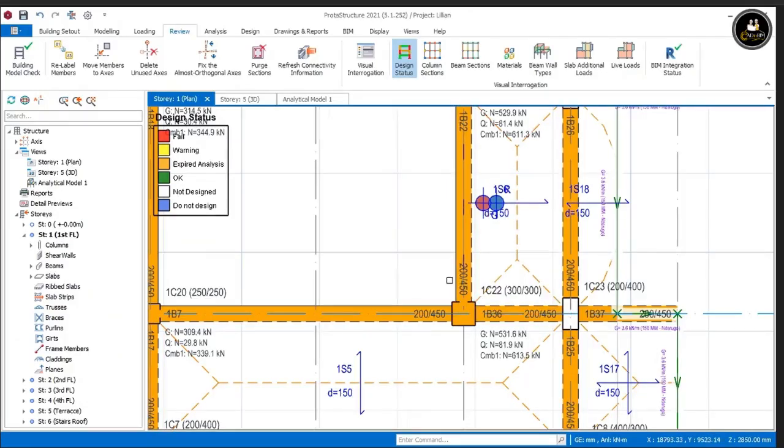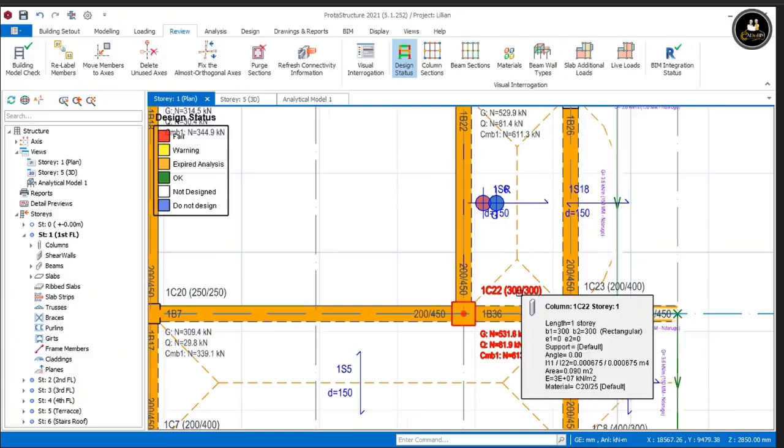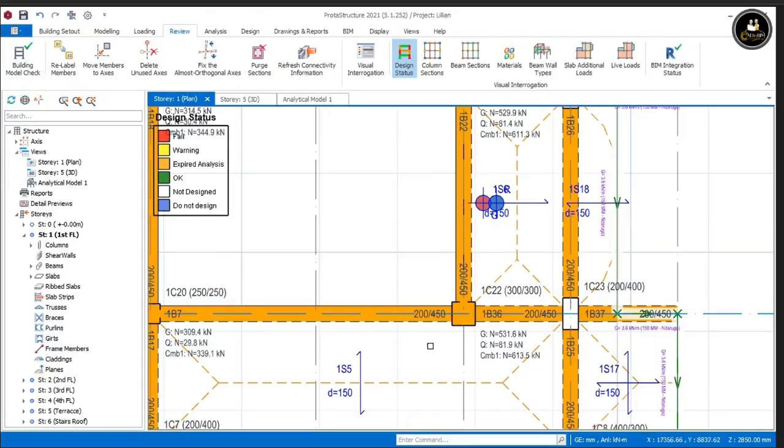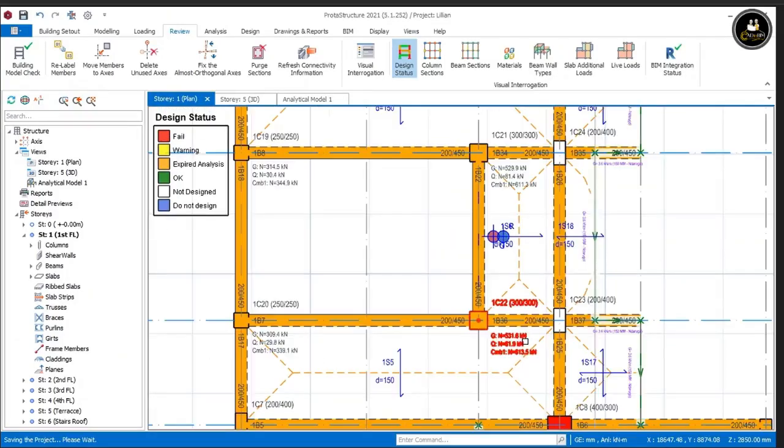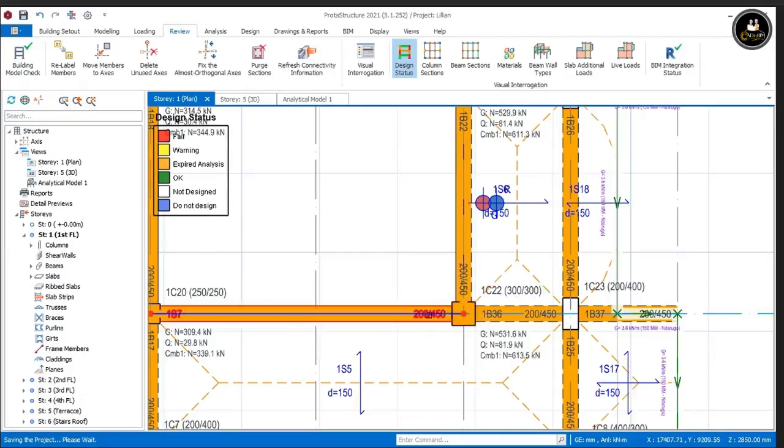No, this one I had put at 300 by 300 to ensure they flush with our beam, our walls. So I can put 400 by 300, no, 200 by 400 rather. And now I push it to be eccentric so that it can pave way for this corridor. You can just align them along the wall, yes, along the wall.